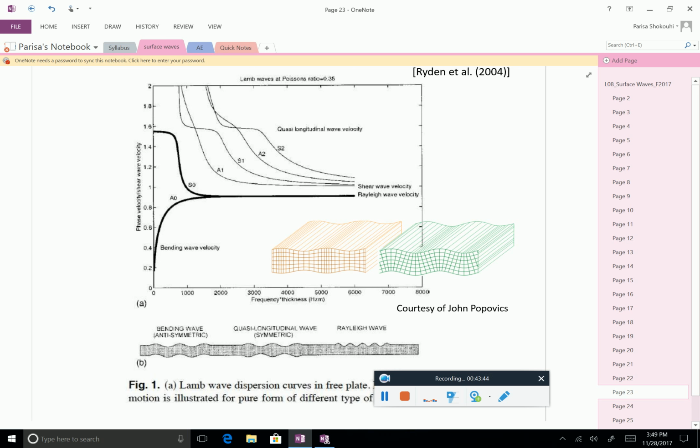It turns out that a lot of times you get non-unique answers, and it's kind of hard to do with two receivers and a source with a dispersion curve. Typically, you use something which I will show you in a minute. You have multiple receivers, and you use a little bit more advanced way of looking at things. To understand that, it's important to talk a little bit about the waves that actually propagate in a plate.